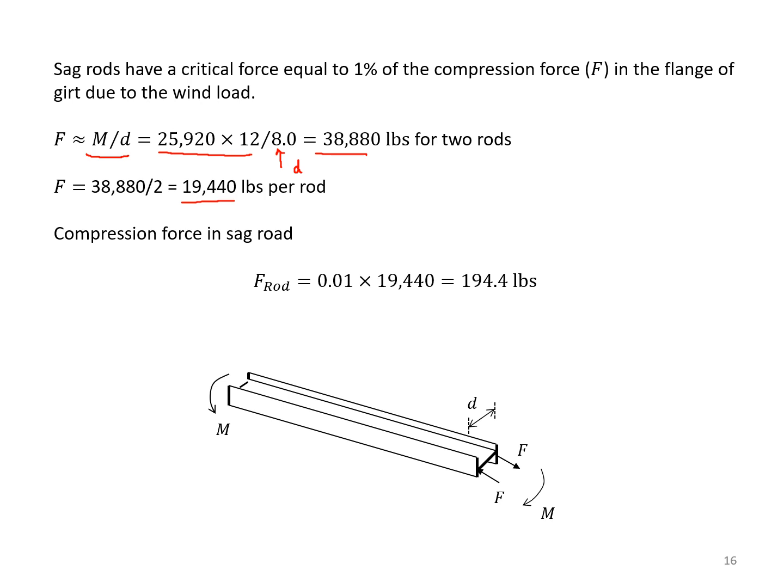And we are considering the fact that wind is acting in this direction. Therefore, we'll have a compression and we have a tension. You see the lever arm, the depth of the cross section for the moments that is shown in here. And by dividing the moment by D, we'll get these forces F.